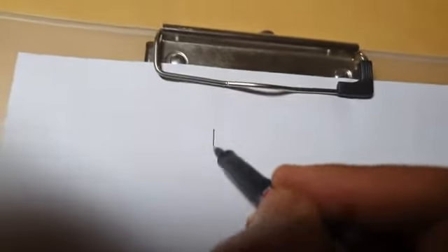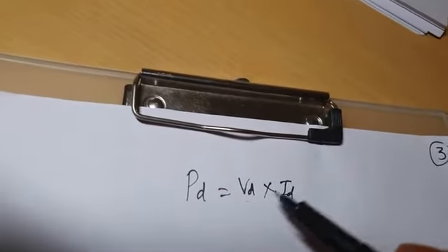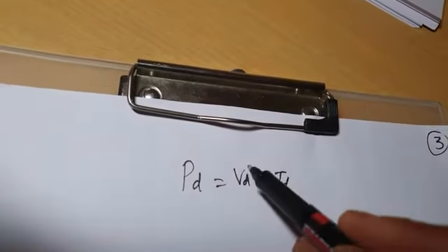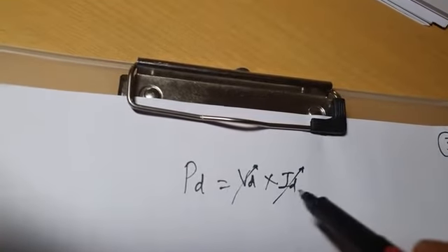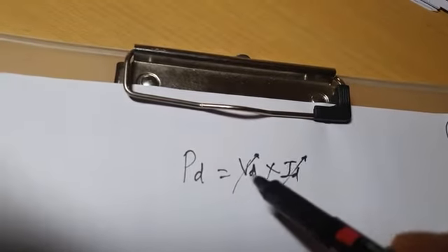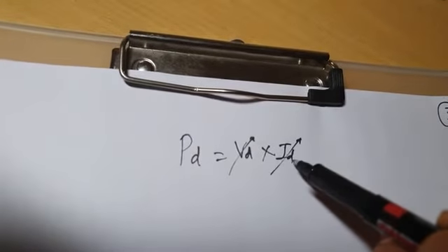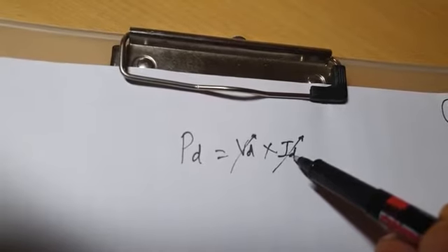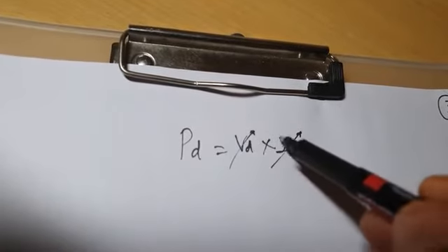The power in the DC link is given by PD equal to VD into ID, the DC link voltage and DC link current. So you can control the power by controlling voltage independently, or by controlling current independently, or by simultaneously controlling voltage and current. But it is always avoided to have power control by simultaneous voltage and current control, because if you simultaneously control DC side voltage as well as DC side current, then your control action will be very complex.